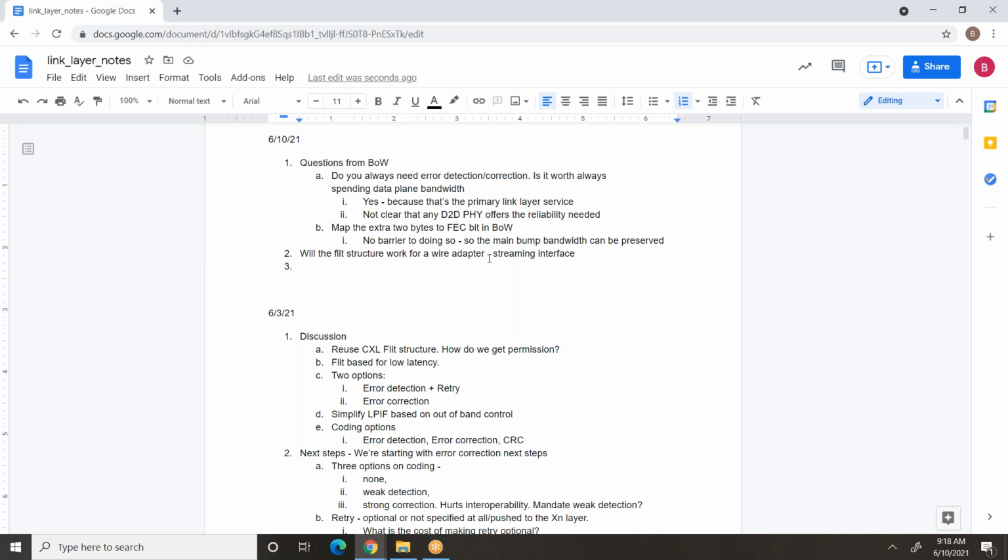I suppose the physical layer would look like a raw, or as you say, a wire interface, just a raw 512 bits in, 512 bits out the far side. Sitting behind it, I have a physical layer which is going to provide some mechanism to frame blocks of data. So add a valid or whatever, or just do it in band with markers. And then above that is the link layer, and the link layer fits into the framing structure below.